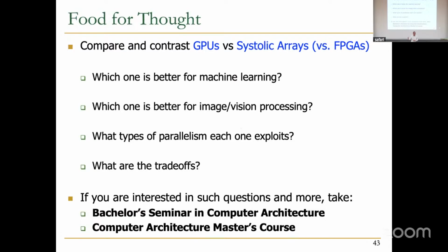And also, as you can see, they're trying to do things such that they're not necessarily bound by a particular model. For example, the tensor cores that are introduced are not necessarily completely bound by purely SIMD execution, right? Over time, people actually change how things work also, right? There's still SIMD-ness over there, but there's also a lot of specialization so that you can customize for matrix multiplication, for example.